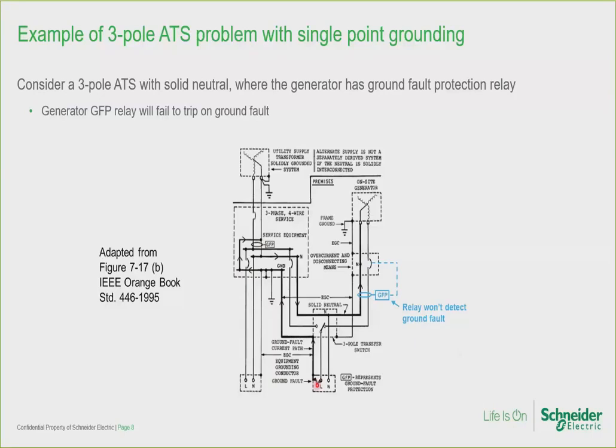The ground fault current flows through the bonding system to the system bonding jumper at the utility source, where it jumps up to the neutral circuit right here. The ground fault current now flows through the neutral back to the generator source to complete the circuit and clear the fault.